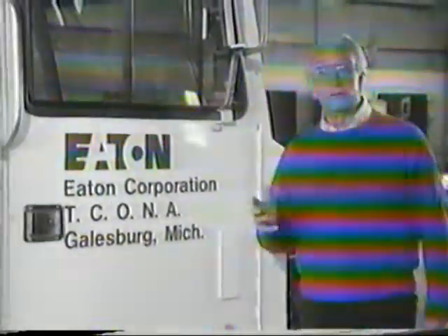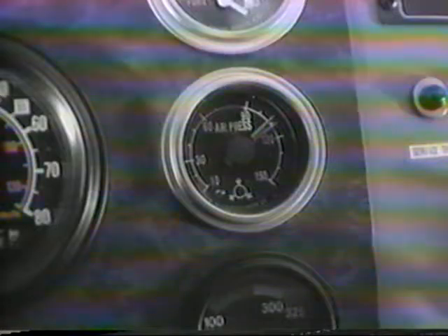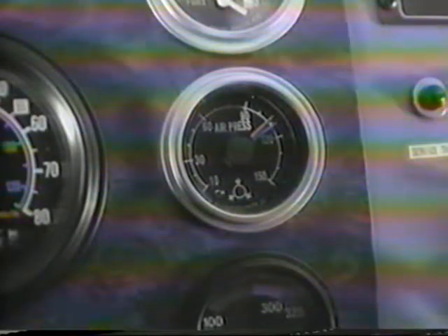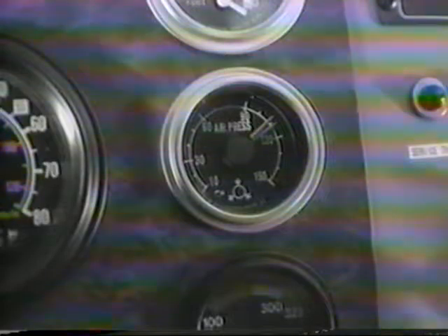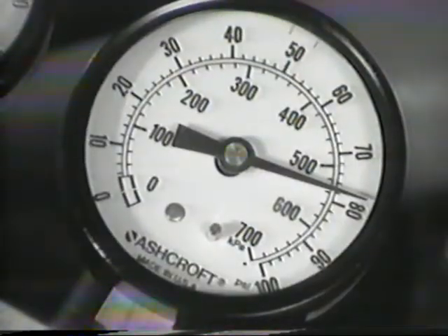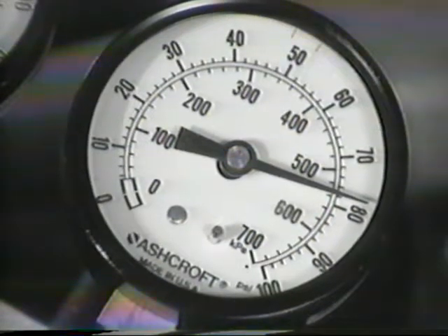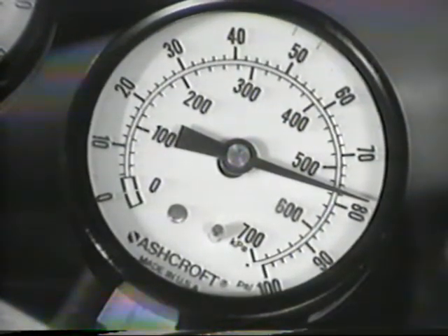This transmission runs on air and electricity from the vehicle. If you don't have enough of either one, you've got a problem. So, for the air pressure test, first install a gauge in the diagnostic port on the transmission air pressure regulator here on the side of the shift bar cover. Start the engine and allow the system pressure to reach governor cutoff. Depending on the truck, that's 90 to 120 psi or 620 to 825 kilopascals or kPa. Pressure here at the transmission should be 75 to 85 psi or 500 to 565 kPa.